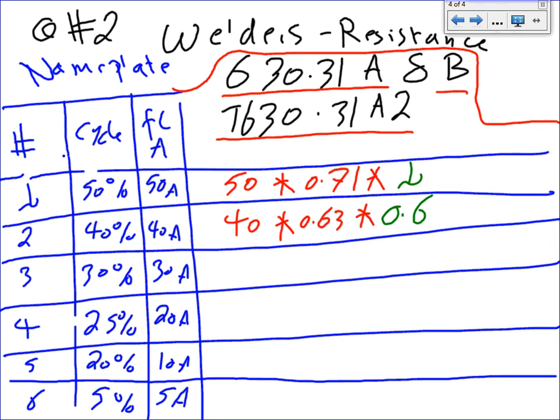The capacity of conductors that supply 2 or more welders should not be less than the sum of the value obtained in accordance with 630.31(A) for the largest welder, and 60% of the values obtained from all the other welders supplied. The capacity of the conductors that supply should not be less than the sum of the value obtained in accordance with 630. After you derate it, that's after you derate it. Then you multiply by 100.